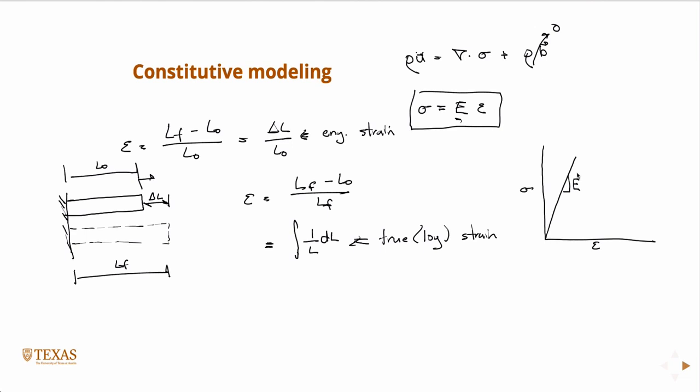Do you really believe that? Believe that any material in the world, if I pull on it, the stress is going to be directly a straight line proportional to the strain forever, and then when I let it go, it's going to return to zero strain. Of course that's not true. I mean, we've all bent a paperclip. It doesn't return to its original shape, right? And if you bend it enough, you break it in two, which means you'd have to deviate from this curve somehow, right?